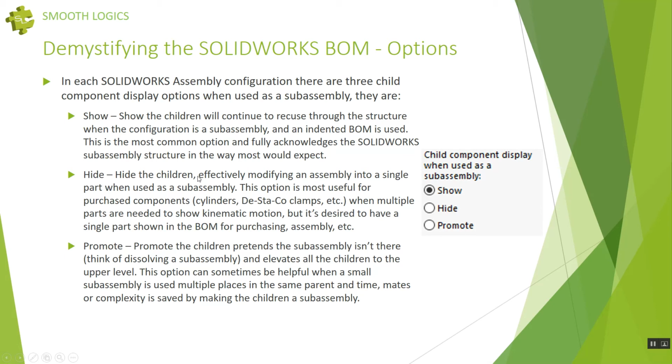The hide option hides the children. So an assembly with no children, an assembly with its children hidden, is from a SOLIDWORKS bill of material standpoint, effectively a part. So you can convert SOLIDWORKS assemblies into SOLIDWORKS parts at the bill of material level, not at the file structure and relational level. That's an important difference to understand. And then promote basically dissolves the subassembly at its higher level in utilization of a bill of material and pretends that the subassembly doesn't exist. That's kind of fraught with a bunch of problems. I see very little use of it in industry and not highly recommended, but it is an option.